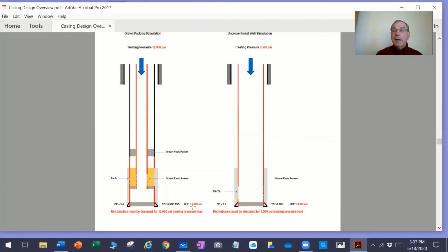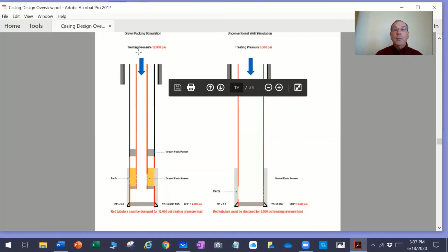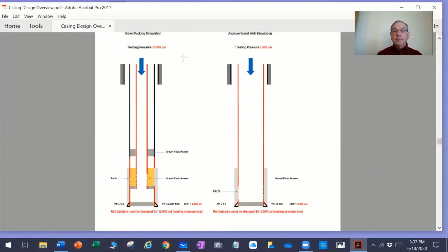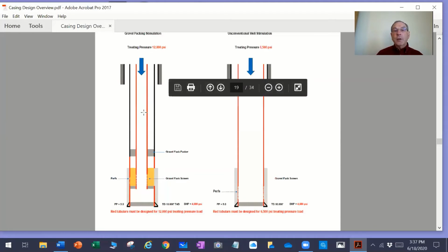So it's 4,600 psi, which is pretty low, but my treating pressure is 12,000 pounds. So what happens when you get a screen out doing a frac pack, you're pumping at 12,000 psi, and most of this pressure loss is frictional pressure loss going down this string, a tubing and drill pipe, that you're using to do this frac pack treatment.